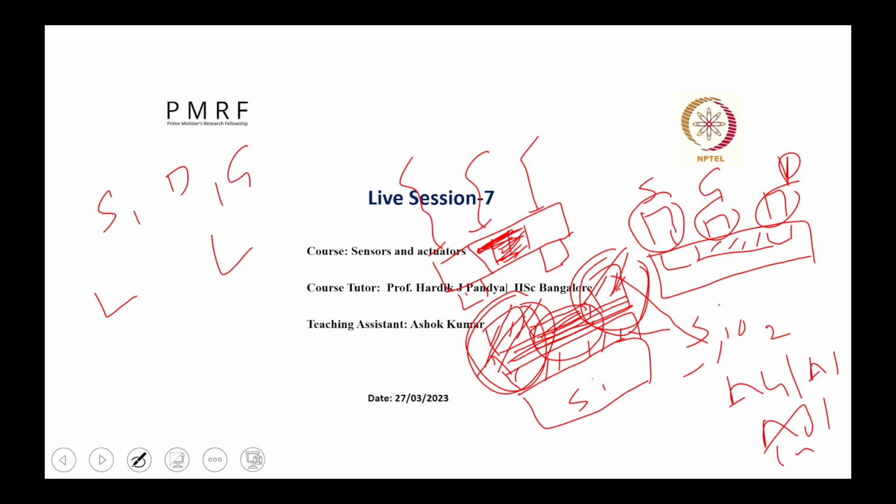Understand? Yes, sir. So as per your requirement, where you want to transfer and what area you want to protect or stay on that sample. According to that, you choose the photoresist, and according to that, you choose the etching material.